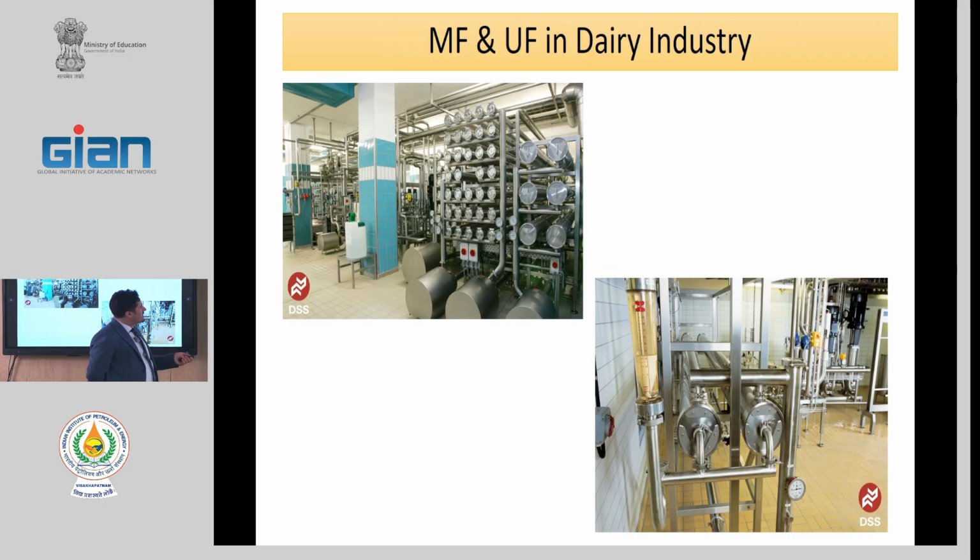You see that this is the pump, and this is the pressure vessel, and all of the tubes are stainless steel. Because for sterilization, every day we use chlorine agent and oxidation agent for disinfection, and all of the systems should be resistant to oxidation, and therefore we do not use plastic or simple metal. Therefore, the dairy industry needs very high capital cost because this pump is very, very expensive.